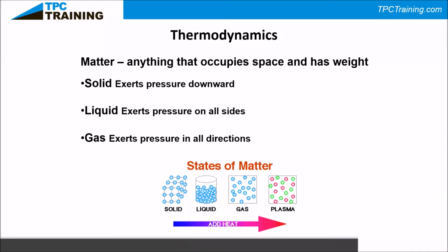In the evaporator, we're taking a low pressure, low temperature liquid and absorbing heat, causing it to evaporate to a gas. Then all that heat we've absorbed in the evaporator, we're going to give off to the outside, causing that high pressure, high temperature gas to change back into a liquid. So we can reuse the refrigerant over and over again.